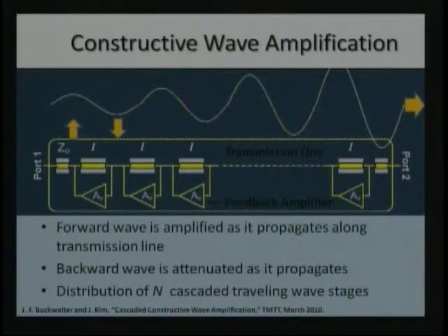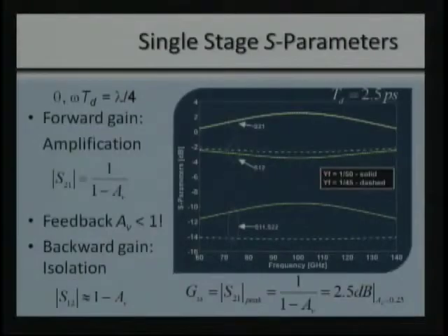But as we start turning up the feedback gain, the S parameters start to bow apart. The S12 must be forced down, and the S21 must be forced up. And so this is a very interesting idea in the sense that a lot of the S parameters are controlled through one parameter, which is this feedback gain.